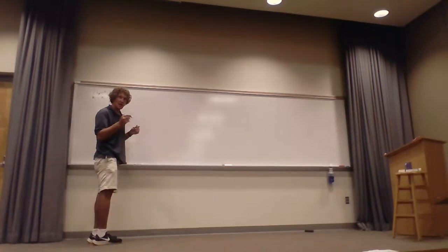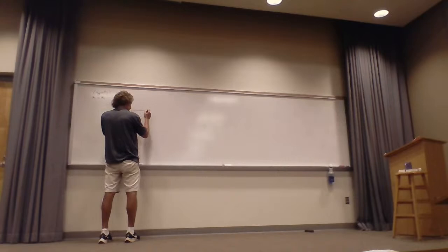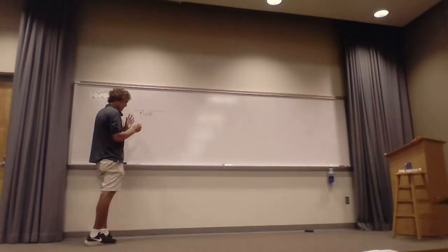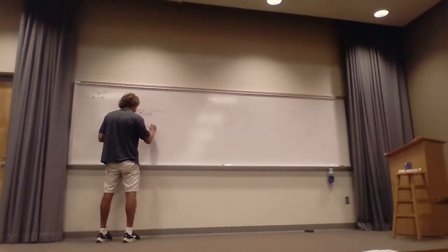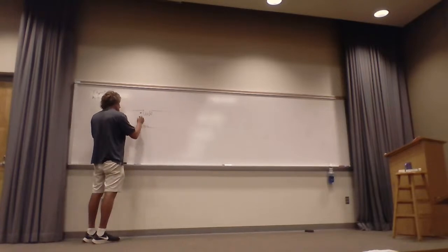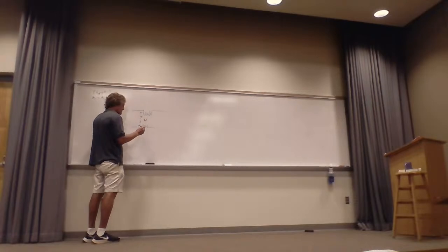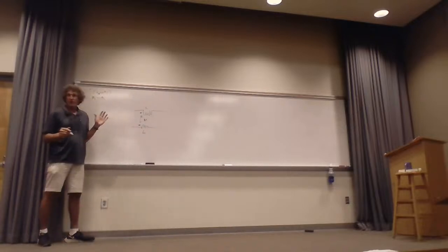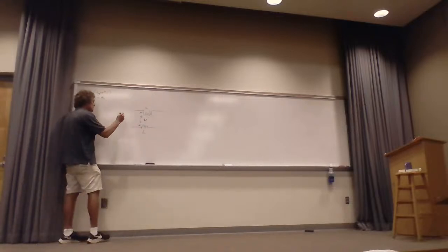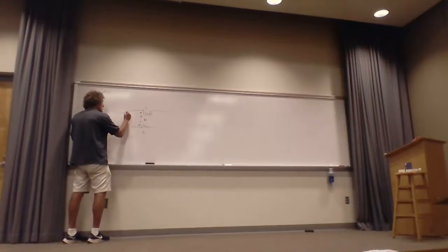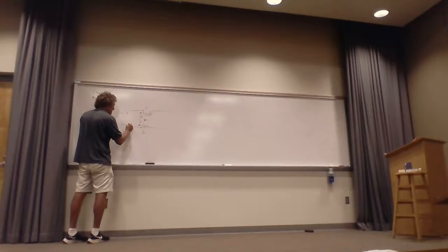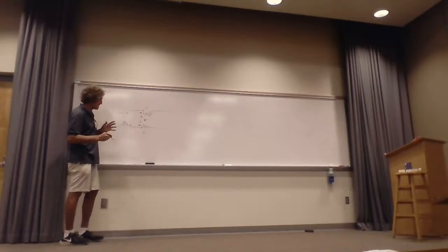Now, when you look at a common mode choke, the way it works is this. Then I'll go through the equations. Here's the dotted terminal, and here's the dotted terminal here, and there's going to be some mutual. Because it always is this way if it's a common mode choke, I'm going to assume this L is this L. Then I'm going to say this has a current I1, and some I2 flowing through the bottom one.